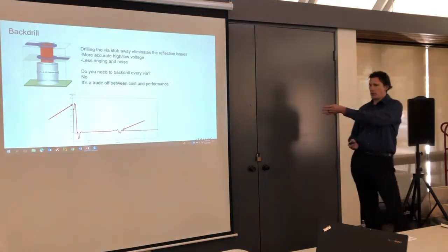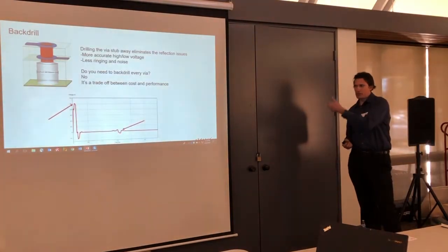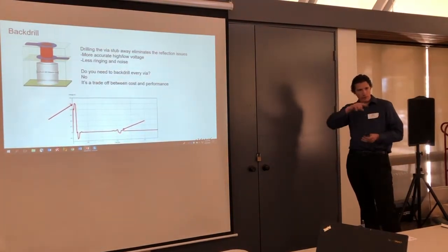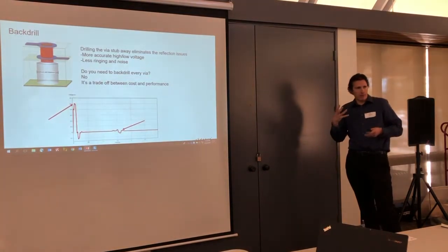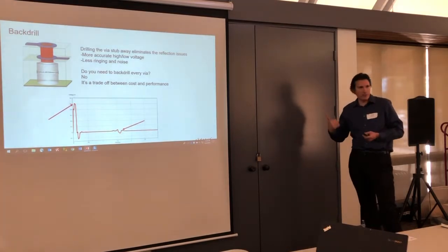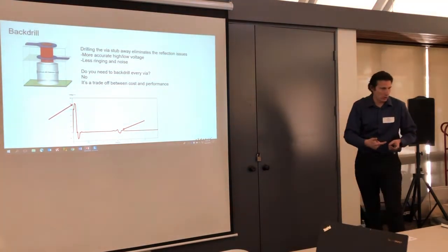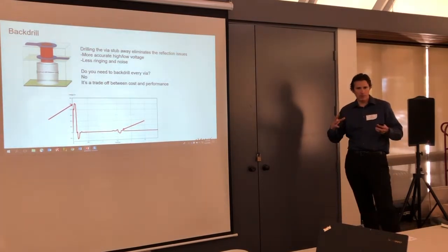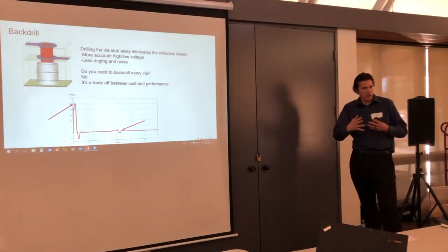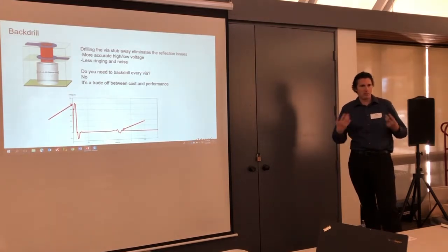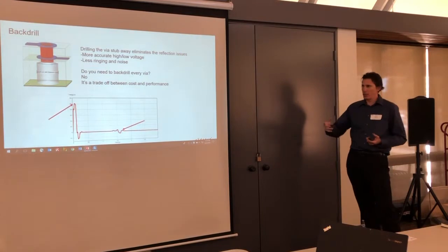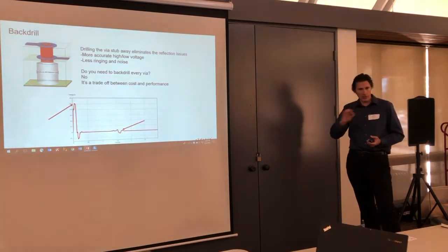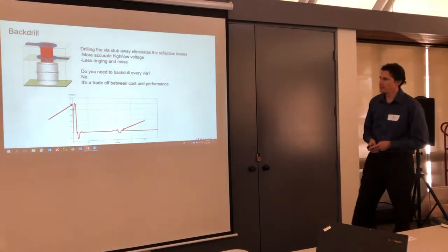And I'm going to start showing you all these effects of issues in a single transition from 0 to 1, so that we start talking about eye diagrams. Think about every time you are listening to a song on YouTube, or take a picture and send it to somebody, or pull up a web page on Amazon, right? The collective amount of ones and zeros that had to be moved to present that data to you is in the millions and billions, and it happens all the time. So getting every single 1 to 0 transition clean and perfect on your system is important.